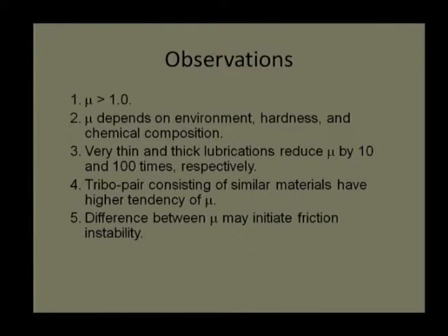Then we say the mu depends on environment, which does not come in ordinary friction loss. It depends on the hardness also. It depends on chemical composition. So, the coefficient of friction from one lab to another lab can vary easily because of these reasons.